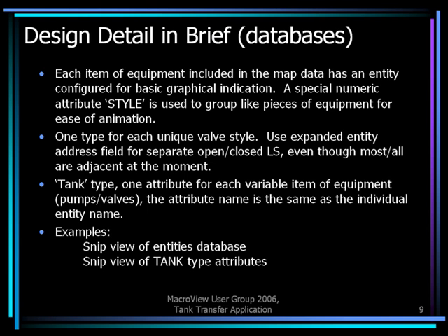The style attribute is used to describe what type of automation level, say, the valve may have: if it's got no limit switches, one or two limit switches, fully automated with an actuator, or what actual type of valve it is. We call that the style, and we allocate a number to that style, so that if a certain personality of the valve changes, say you decide to add an extra limit switch, you keep the name of the valve and you just change the style number, and all of a sudden it is handled differently by the system.